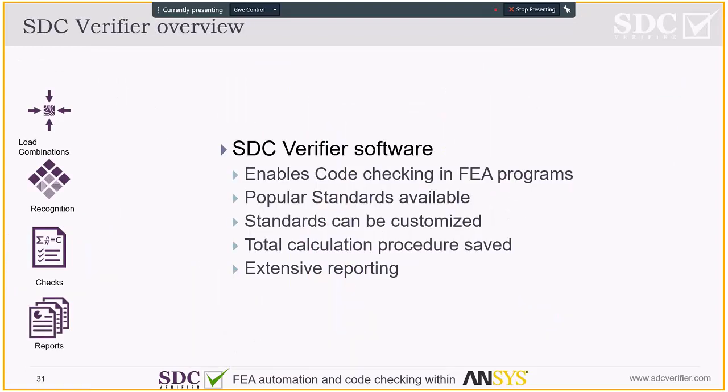So the main benefits of SDC Verifier software is that it enables code checking in your finite element program in Ansys. So you don't need to use some dedicated software to build another model to do the code checking. You have your model for the calculation, and you use this for code checking as well. We have a lot of popular standards available, and it's customizable, and you can write your own.